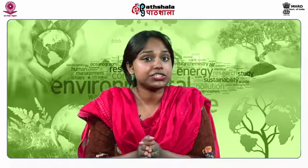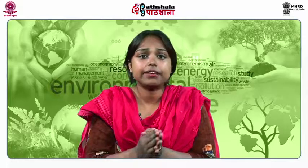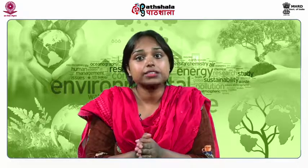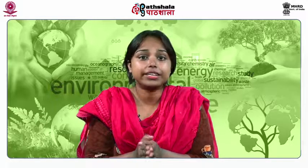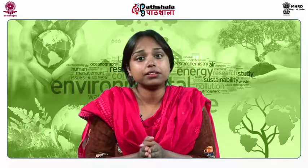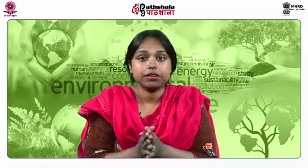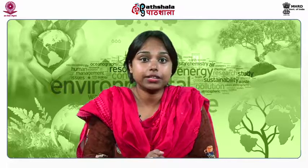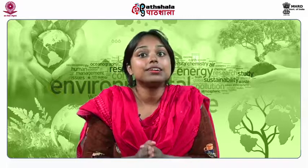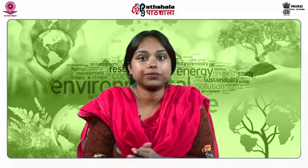The gasification agent utilized in the method allows the feedstock to get effortlessly altered into gas by the assistance of diverse heterogeneous reactions. Gasification based systems make it promising to achieve high power generation and efficiency, which cause carbon dioxide to get generated in intense form, plus it is easier and cheaper to capture and sequester it, thereby preventing it from reaching the atmosphere. Now, case study 3.